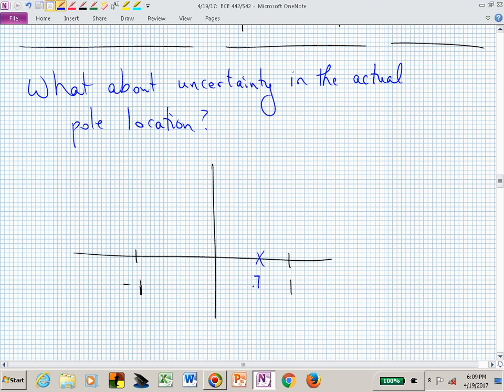There's the plant, the true system, and you modeled it as a pole at 0.75. What did your controller do based on this? Well, now your controller, can I put the controller poles and zeros in red just to distinguish them? You have a PI controller that you put a pole at 1, and where did you put your 0? At 0.75.